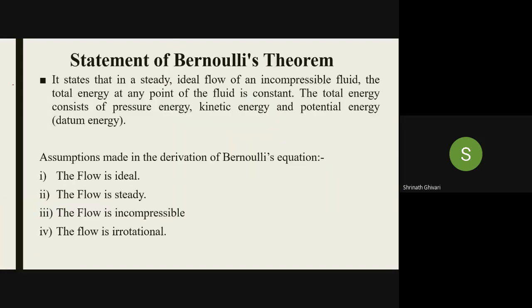What is the statement of Bernoulli's theorem? It states that for a steady, ideal flow of an incompressible fluid, the total energy at any point of the fluid is constant. So the total energy, that is p/(rho g) plus v squared by 2g plus z, is equal to constant. The total energy consists of pressure energy, kinetic energy, and potential energy.